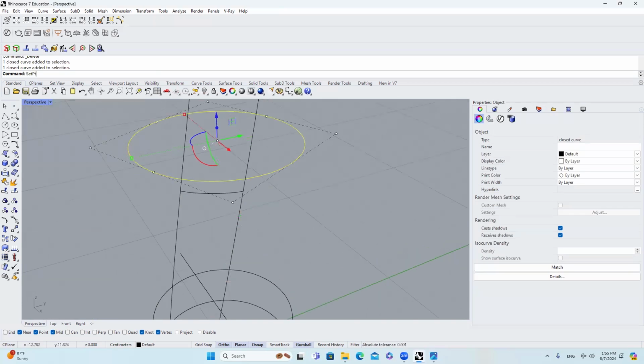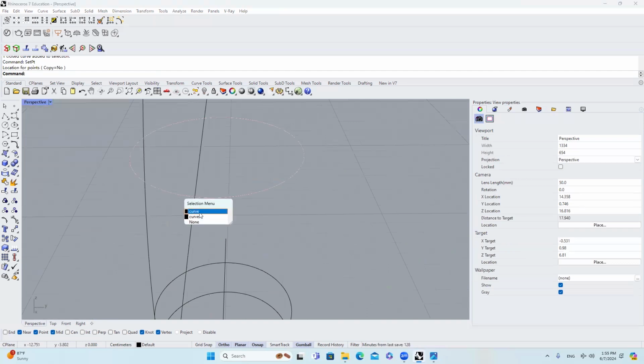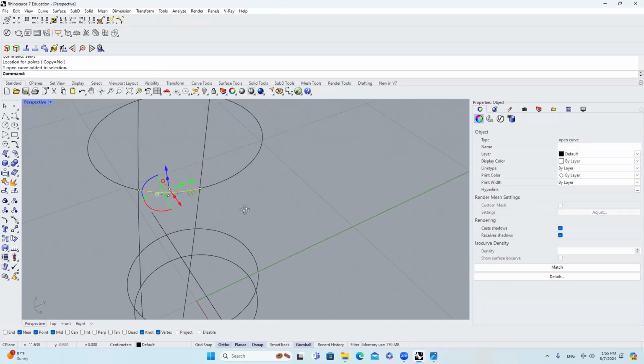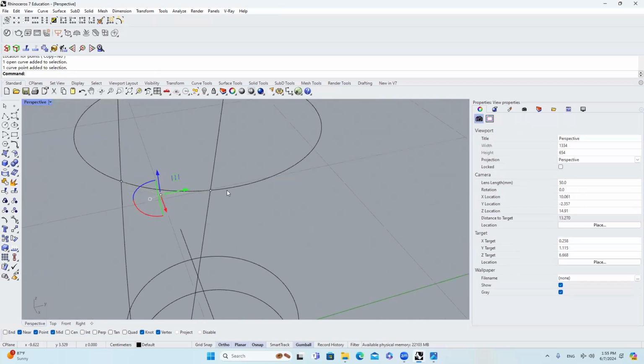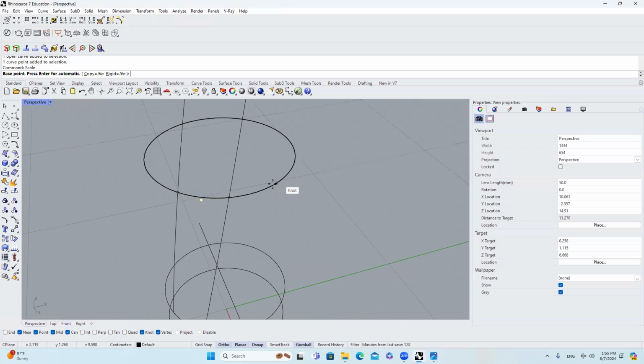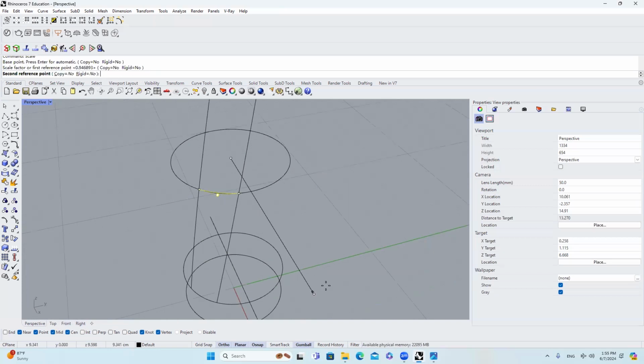So the next thing I will do is I will select this, set it PT to the Z direction. So they are on the same direction. Basically, I'm selecting this arc, and I will select the central control point. And then I will type in scale, and I will choose the center of this curve. So click, make sure you have center clicked, and then I will select it. And I will move in just a little bit.